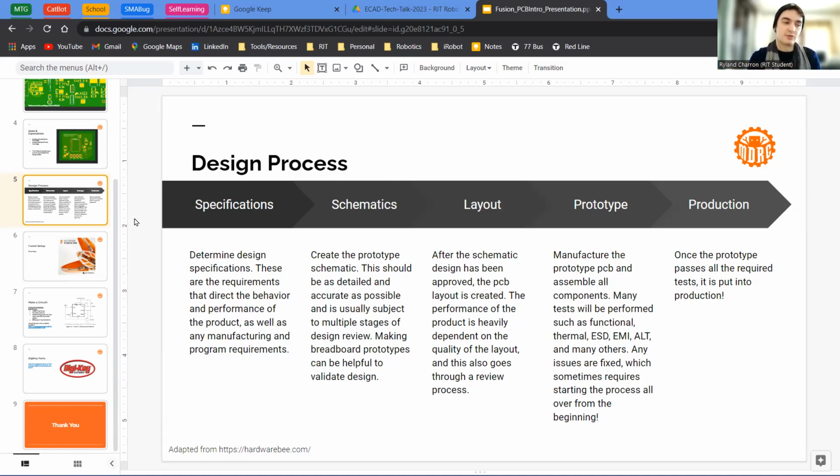For example, there's class 1, class 2, and class 3. For PCB design and soldering, class 3 is military grade, and class 1, I think, is a sketchy Amazon product. Most companies operate in class 2 to class 3, but you don't need to care about that at this stage. But that's where a lot of those design factors would come into play.